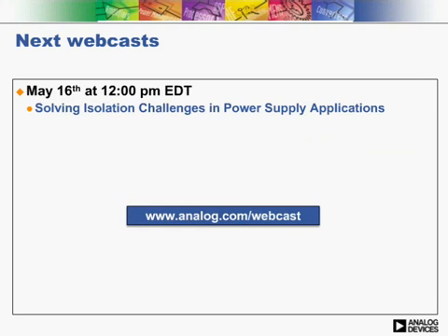Thanks, Chris. That's an excellent question. Deterministic latency is important in many applications. These would include complex IF for communications applications, and multiple converters in a mil-aero application such as radar, where multiple converters need to have a known timing relationship.